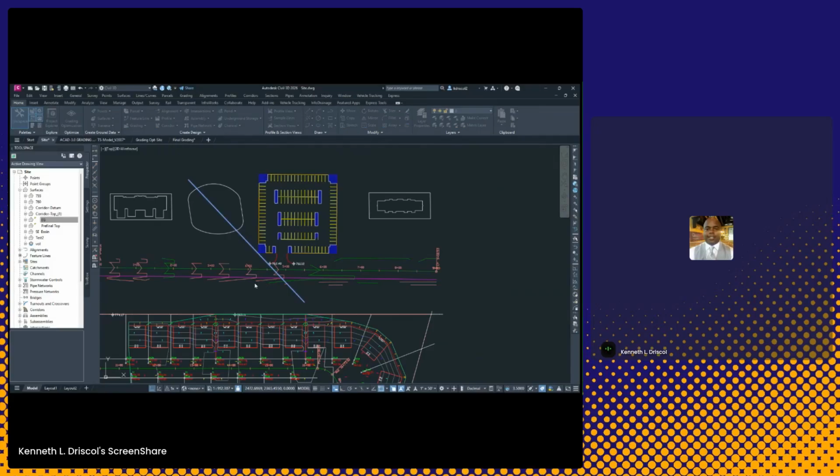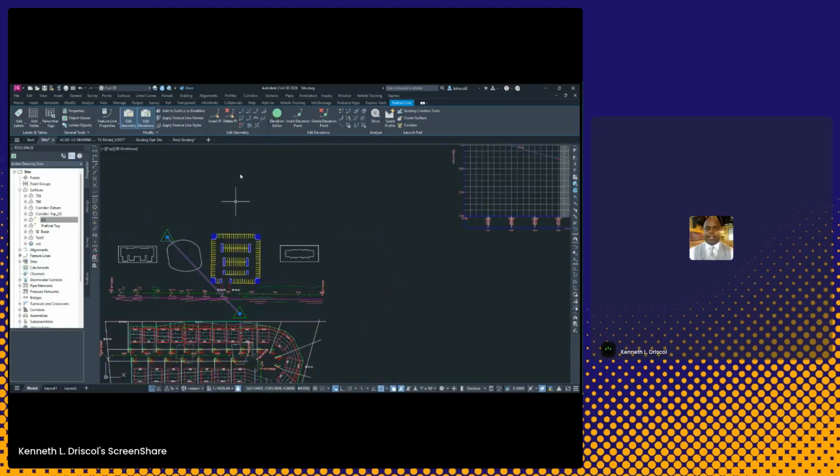From this feature line, I'm going to assign elevation. I'm going to say 763. I'm going to say right here, I'll pick on the feature line. Right now, with this feature line, I'm going to say, I want this to be here from the top, 763, coming down in terms of drainage, negative 2%. We're going to make it work out.